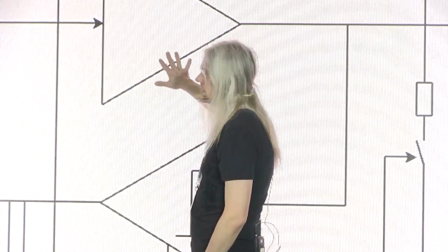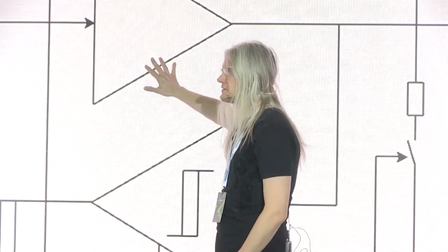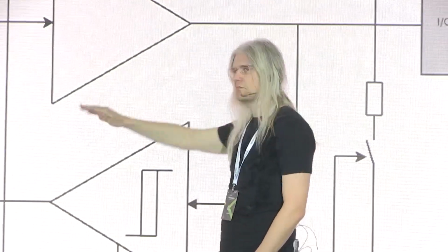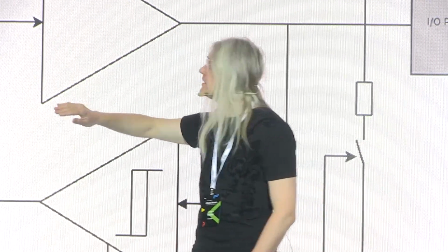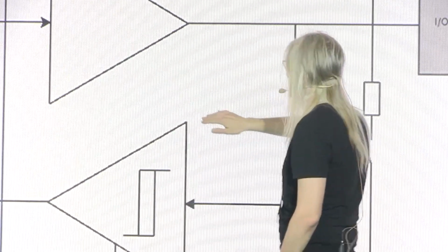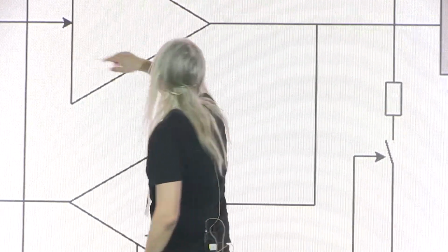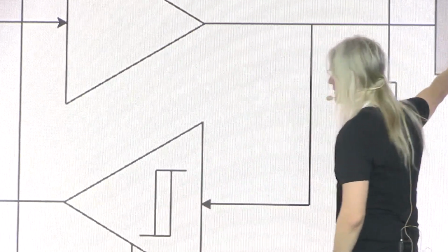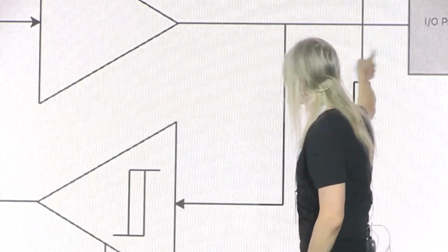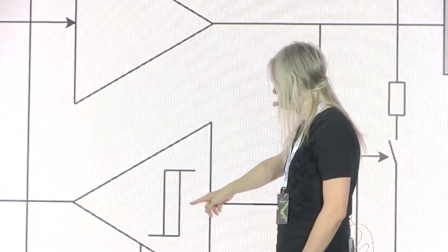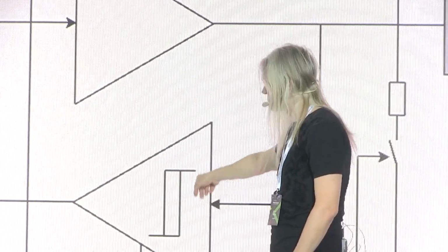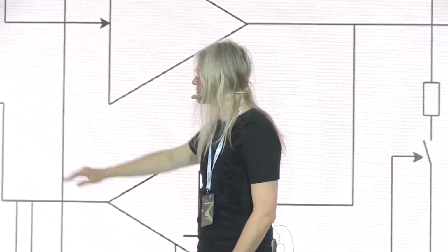This thing is an operational amplifier that you know from your education. Has somebody not seen an operational amplifier? Does everybody know what the totem pole output is? Yes, you do. Okay, good. Did anybody understand anything? This is a driver that drives this signal in an amplified manner out there. And here, from the same pad, you have an input thing with something called a Schmitt trigger that reads the same input back in.